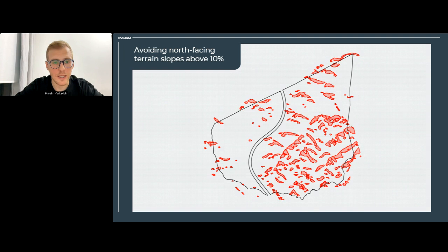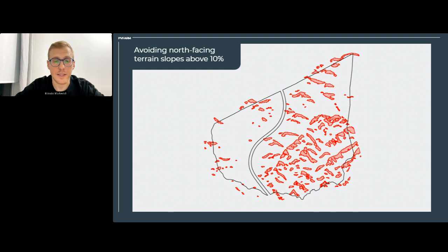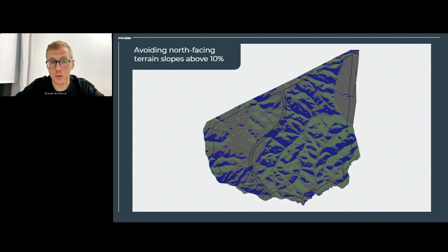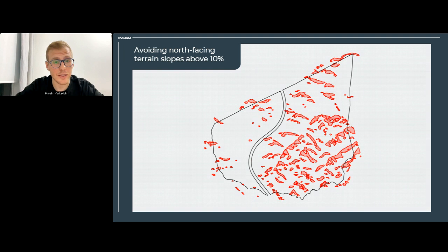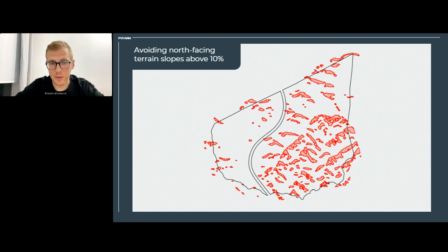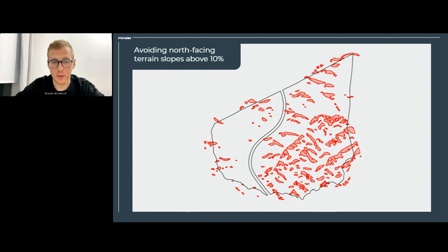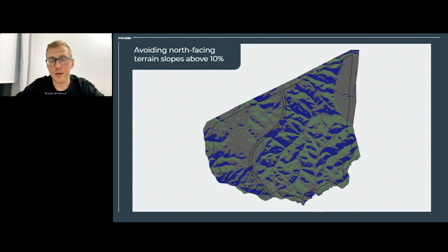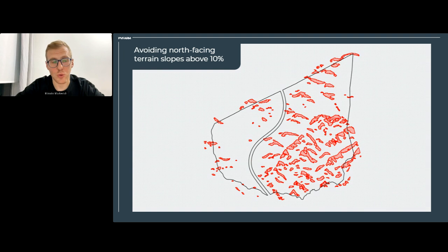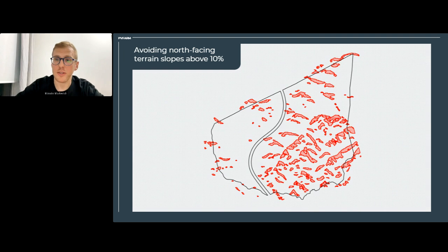But in most cases, how people do it today is analyzing terrain, analyzing the surface, finding those slopes, then creating boundaries, exclusion areas, and then populating the layout with trackers, avoiding those areas. That's one way of doing things. Another way, as we showed through insights, is that sometimes it is much better to place trackers first.